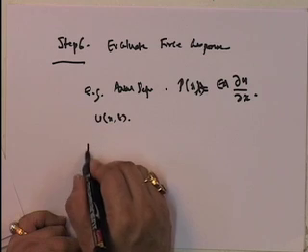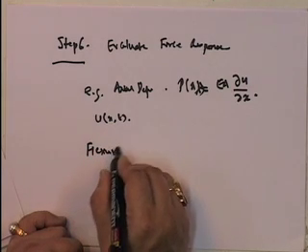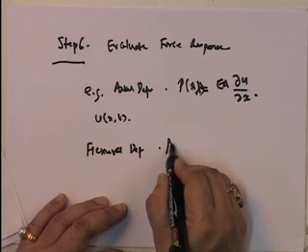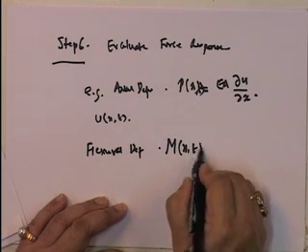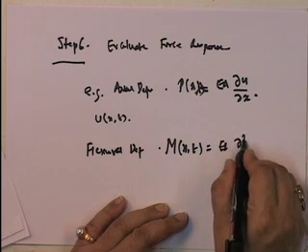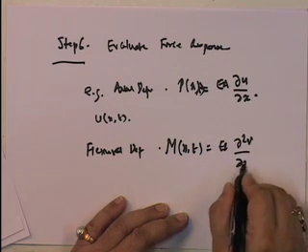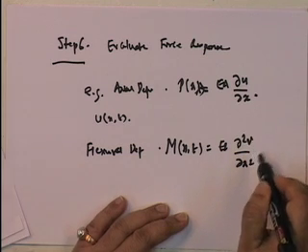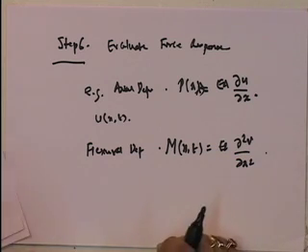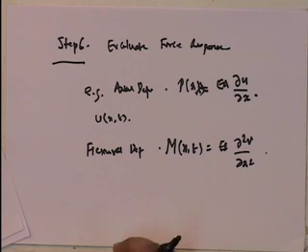And then if you have flexural deformation, then moment M of x and t would be equal to EI into del squared v by del x squared. So you can evaluate the force response, and that is it. These are your dynamic analysis steps for a continuous system.